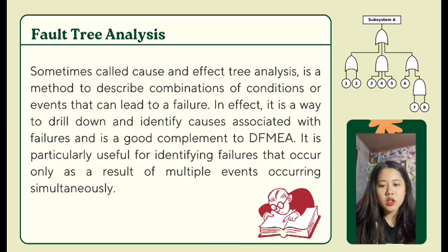Fault tree analysis, or the FTA, sometimes called cause and effect tree analysis, is a method to describe combinations of conditions or events that can lead to a failure. So in effect, it is a way to drill down and identify causes associated with failures and is a good complement to the FMEA. It is particularly useful for identifying failures that occur only as a result of multiple events occurring simultaneously.